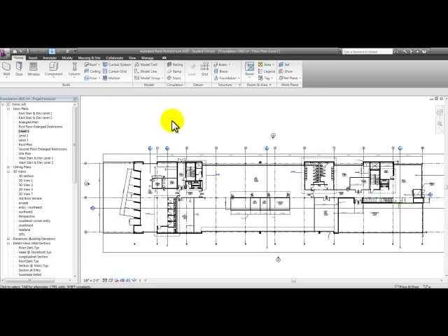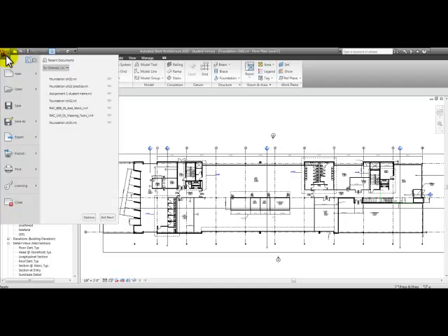In the upper left corner of the screen, you can access the application menu by picking on the large R. Here you will see commands like save, export, and print. You can also access recent and open drawings by order list, date, size, and type. Use the push pin button to the right of these files to keep a file in the list. It will display at the bottom until you pick the push pin again to turn it off.